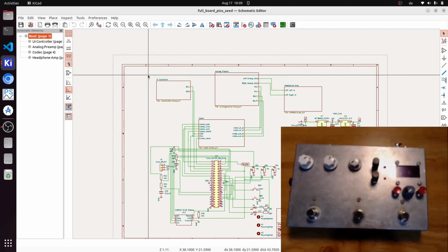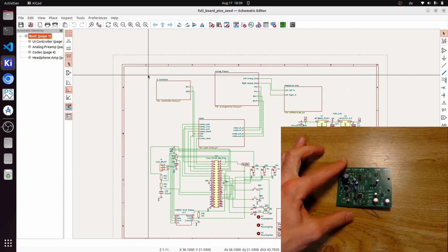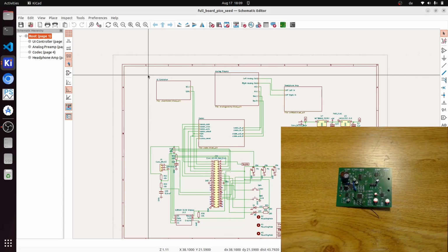So, for this board, this required a few more connections to make, or a few extensions, I built another PCB, which is this one, which I dubbed extension board, and this allowed to connect the foot switches and to have all the symmetric ins and outs and so on, and also a little EEPROM to save presets, and an additional microprocessor to handle the stomp switches and so on, to talk with the Raspberry Pi Pico.